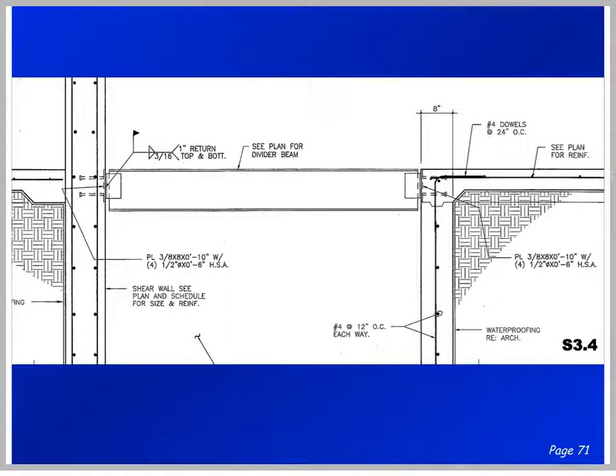With even a closer look at this steel beam, the part that the concrete contractor would typically be responsible for is the embed, and how the embed is attached with these double-sided bevel welds that are 3/16 inches, 3/16 inches fillet, 1 inch returned top and bottom. This is why we call them details. You get a lot more detail.